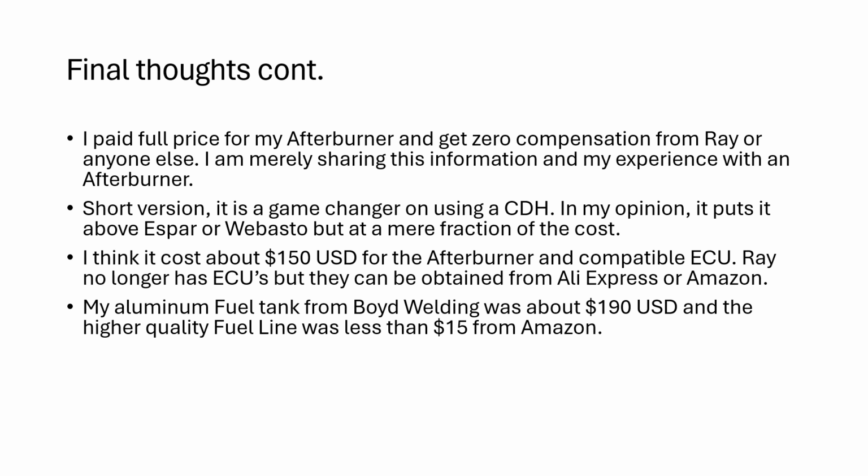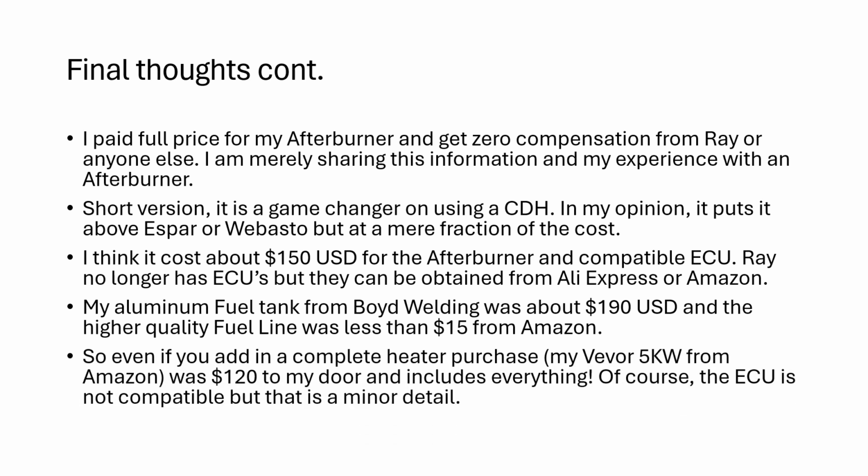And I also replaced the soft green fuel line that was with the cheap kit with the high quality S-Bar fuel line kit from Amazon. It was less than $15. So even if you had to buy a complete diesel heater because you didn't have one, I bought the 5-kilowatt Vevor from Amazon. It was $120 to my door, and it had everything. It had a tank, pump, lines, harness, etc. Obviously, the ECU is not compatible, but that is simple enough to fix. I actually have a compatible one as a spare that I carry with me in my camper.